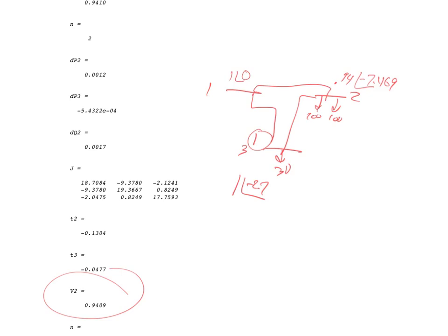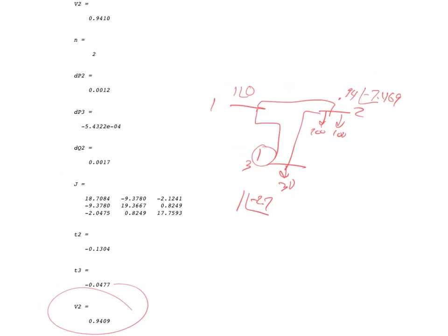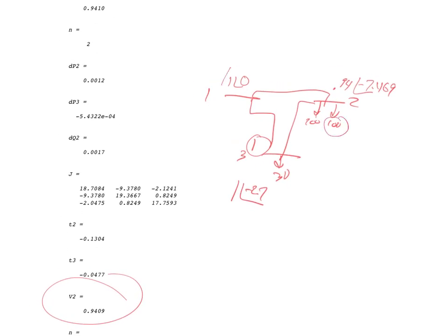So, you've got to sanity check it, right? Because we're engineers, or almost engineers. We've got to make sure our results make sense. So, does reactive power flow from a higher magnitude to a lower magnitude? Well, I didn't calculate my delta Q2, so you can't tell here, but clearly I can see that I've got 100 megavars flowing here. So you've got some reactive power going in there. I think this is actually 63, is that correct? It's 63 in.